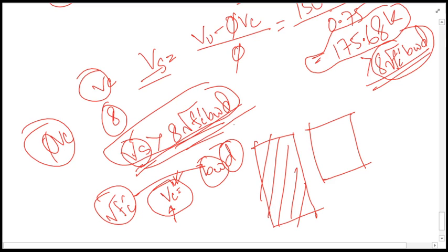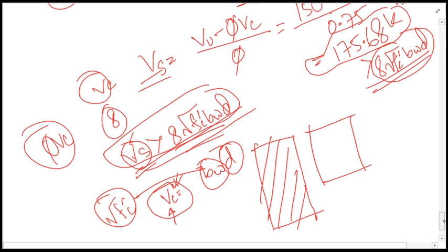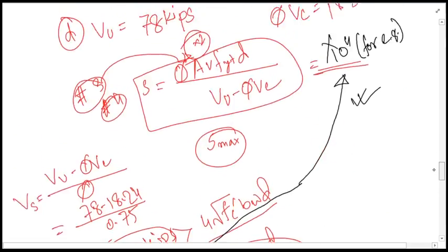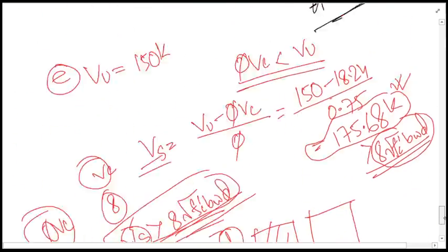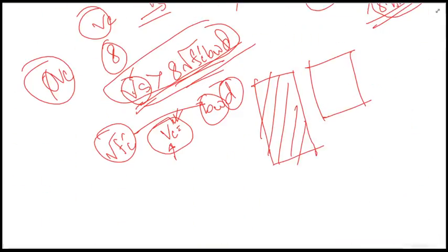And I have said that from the calculation, the maximum for 8 individual 2D frames, if you have 8, that is better. If you have 10 or 12, as many frames as you have got, for each frame the maximum shear value, taking that value you will be designing the shear reinforcement distribution accordingly for all the beams of that particular frame.